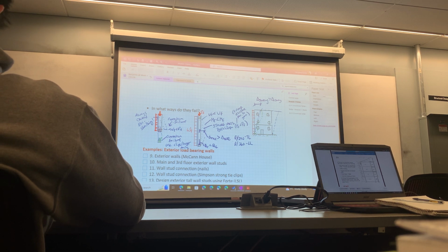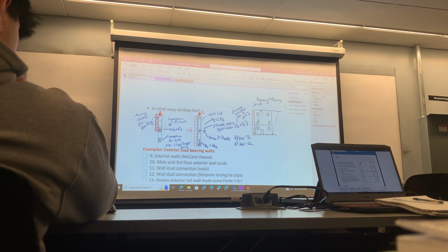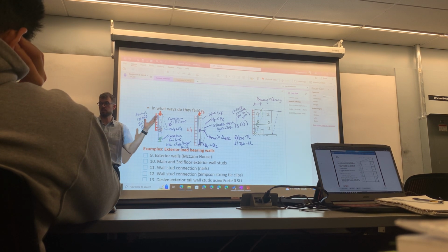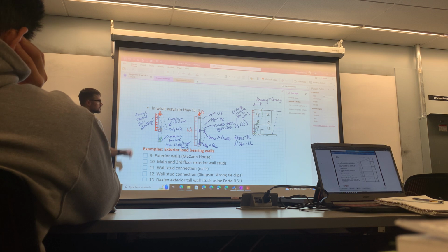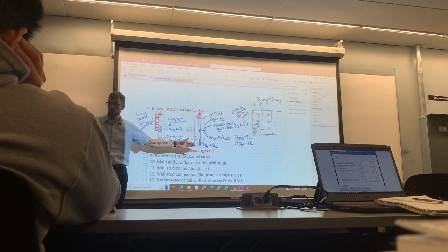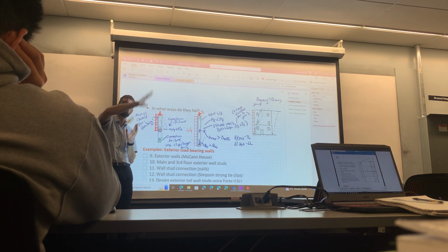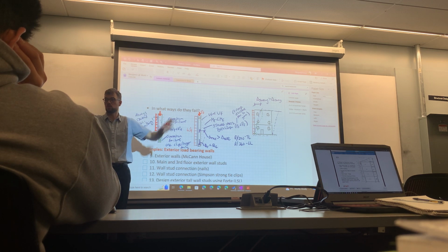No. These will be built solid enough that they can withstand those temporary forces. Because pre-test, we need to check things like this. Maybe that's because of the dead load of concrete. Yeah, makes sense. Also they tend to be very long and slender. These guys here, you're usually not erecting more than 9 or 10 feet at a time. When you go to build the tall walls, that's where you might run into an issue. But you have the whole 3 sides of the building built, and you're leaning up big posts, big studs, connecting them in, and you build those ones in place.